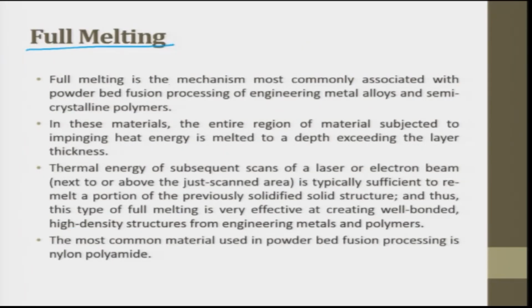Full melting is the mechanism most commonly associated with the powder bed fusion processing of engineering metal alloys and semi-crystalline polymers. In this material, the entire region of material subjected to impinging heat energy is melted to a depth exceeding the layer thickness.